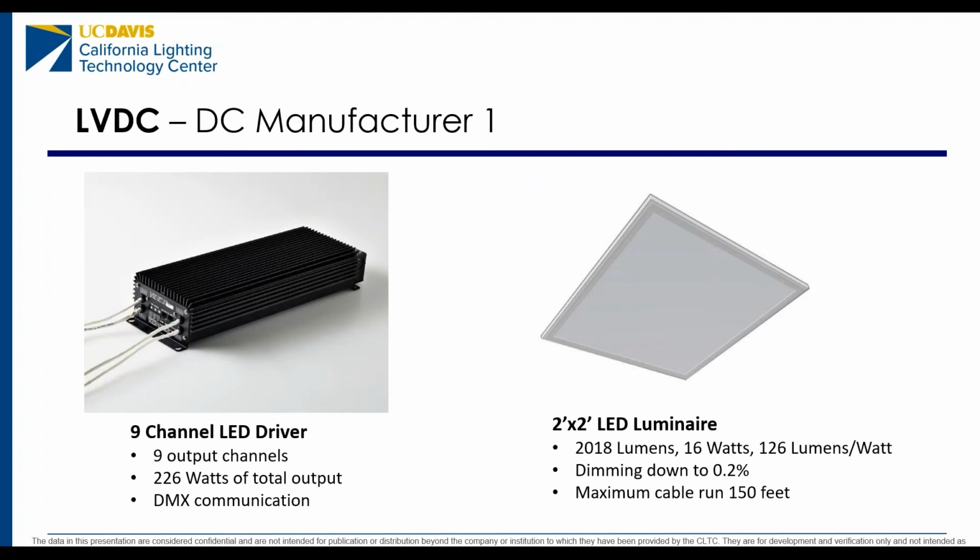For the low voltage DC system, we purchased this 9-channel LED driver. It has 9 output channels with a maximum of 226 watts of DC power. It communicates via DMX protocol. And as a load to this power supply, we procured 9 2x2 LED luminaires with 2,018 lumen output at 16 watts, or 126 lumens per watt. They're capable of dimming down to 0.2% and have a maximum cable run between the power supply and the luminaire of 150 feet. Two things to note at this point.